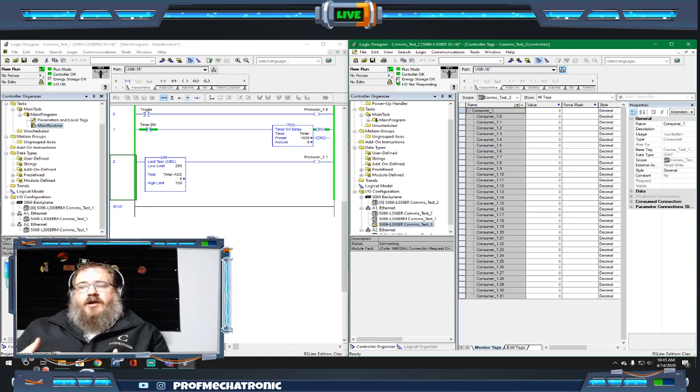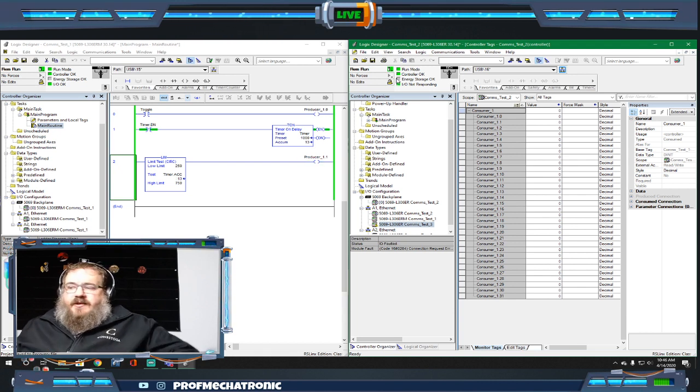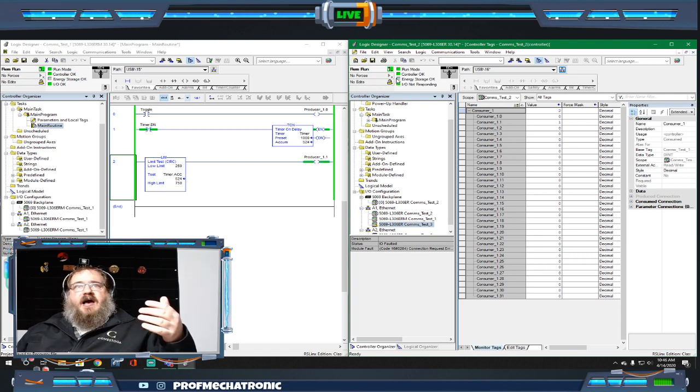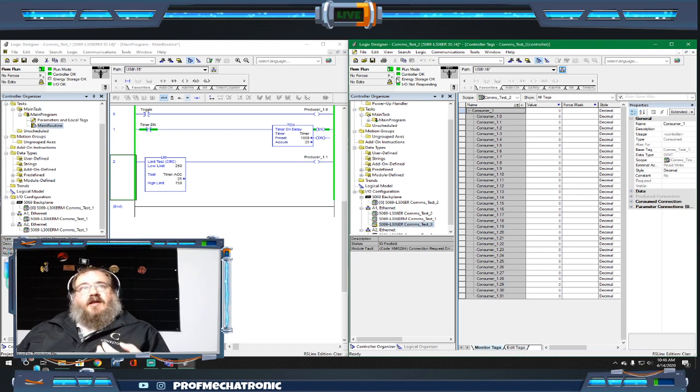This is really important in the world of getting PLCs to communicate together. It's really important to really have the communications between cells figured out. Some of the advantages to this stuff is that you can actually have multiple cells transferring multiple pieces of data to do lots of things, right? You could actually have a bit turning on to pass, say that I've passed you a part, right? That's a nice, easy, simple one, right? But you could also use it for RFID tags, quality information.